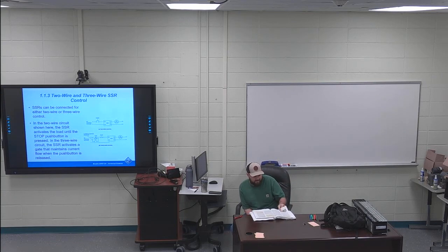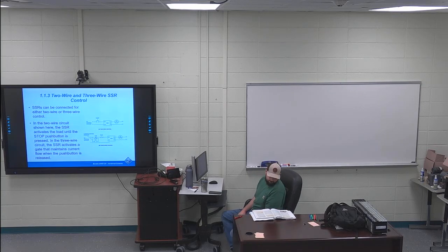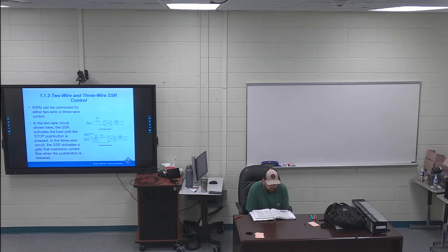Moving on to page 8 and 9, in the programmable SSOLRs, the right-hand side of the page, the sentence that's right before the bullet points is highlighted. The types of functions and trip thresholds that can be programmed with most programmable SSOLRs include the following. I've got the first bullet point, the heading highlighted, overcurrent trip class, with the second sentence. Class 20 is used for most NEMA-rated general purpose motors. That class 20 trip setting is used for most NEMA-rated general purpose motors.